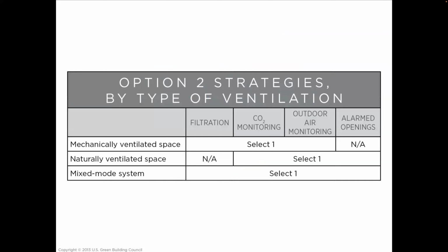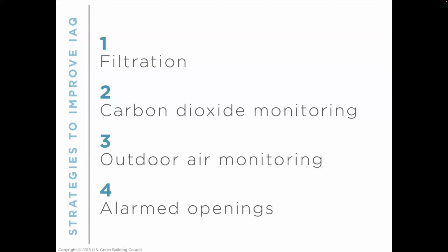All right, and then some enhanced option 2. You want to increase outdoor air monitoring, increase filtration, monitor CO2. Again, alarmed openings. So if you have a naturally ventilated space, you want to know that the spaces are getting opened. So again, these are things you need to do.